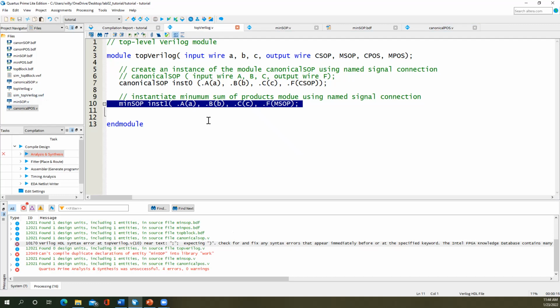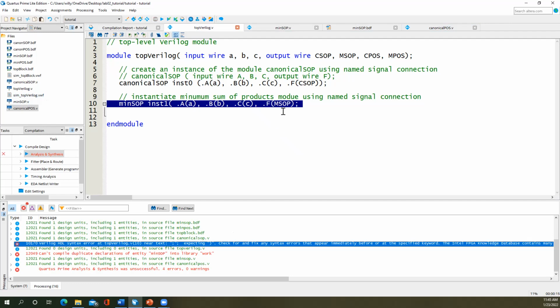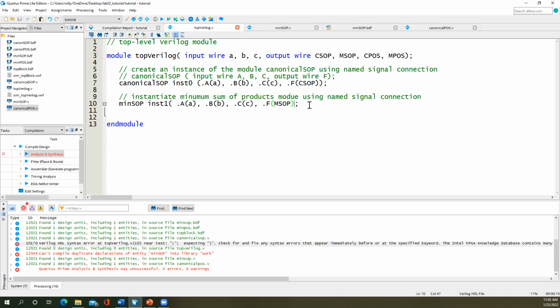All right, so I didn't run that over here. This says I have a syntax error. HDL top. A lot of times when it gives you an error, this is telling me the name of the module, top verilog.v, line 10. A lot of times when you double click, it will take you there, expecting a parenthesis and it got a semicolon. Sometimes they can be on the line above. Dot A, dot B. Oh, I'm missing the last parenthesis here. I often forget to do that.